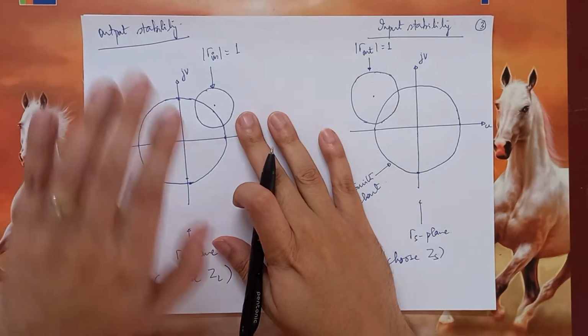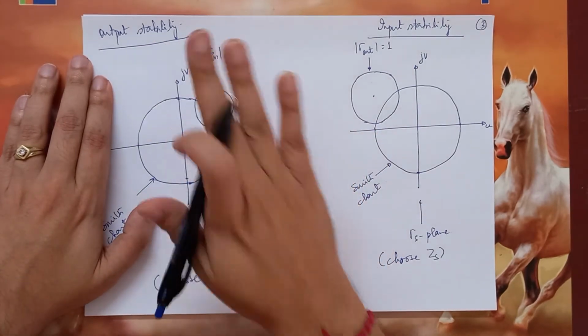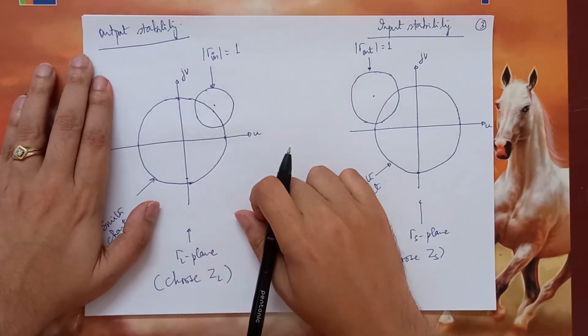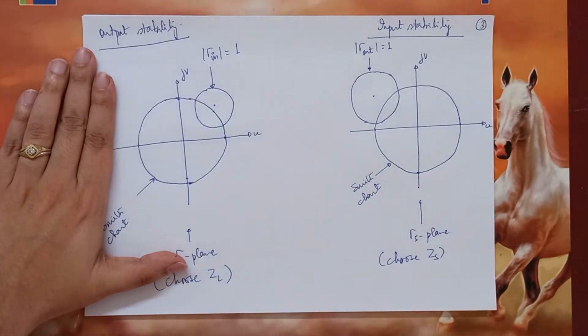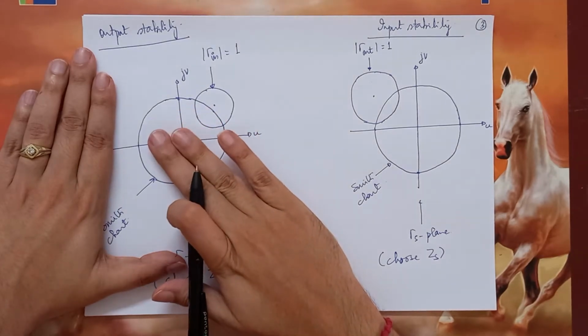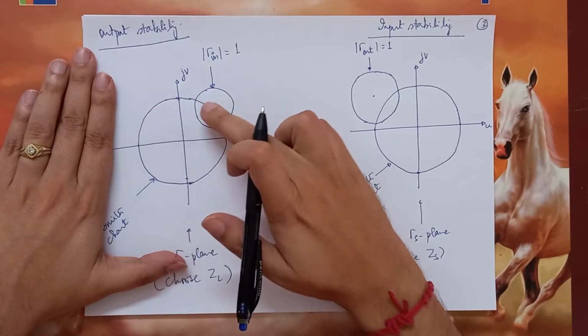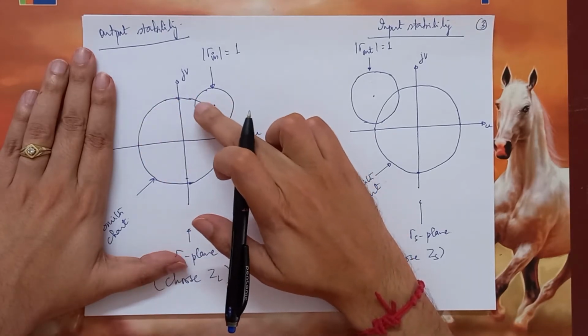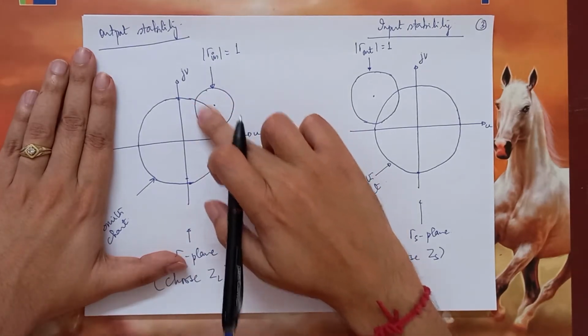Now, we are not sure how to proceed from this point. All we know, let us consider for the time being the output stability circle. The stability circle is over here. The choices for us to choose the impedance is either this larger area of the Smith chart or that part of the Smith chart which is overlapping with the stability circle, that is this smaller region.